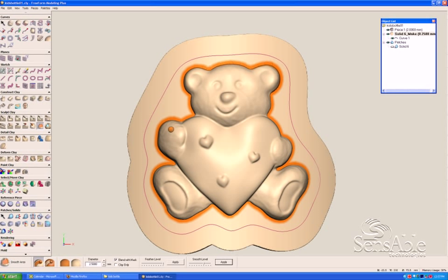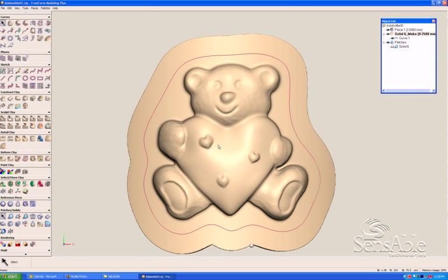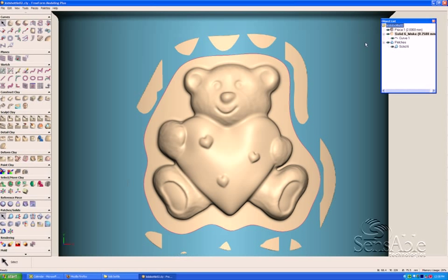So right now I'm using my smooth tool to paint the seams of this design so that we can blend in the edges and give it a nice rounded radius. This is kind of a replacement for a fillet tool in some cases, and it's used to get rid of unwanted data. In this case, it works really well for blending in this seam.